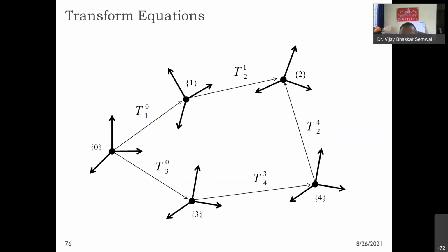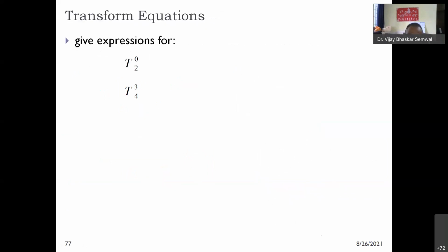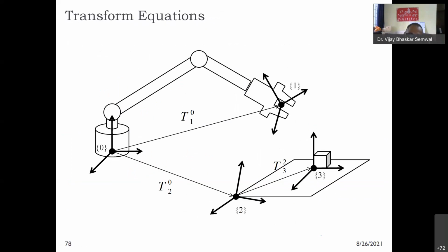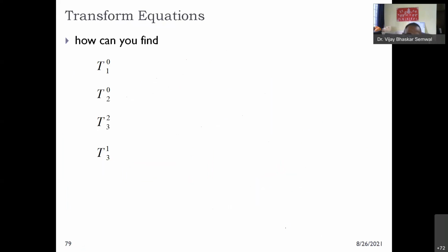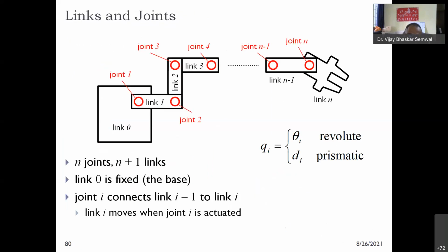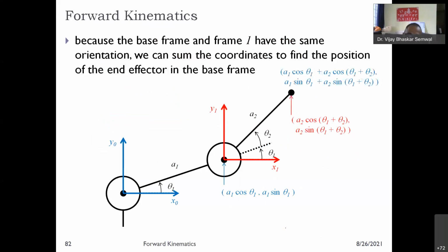matrix equation. So in forward kinematics, we are moving like frame 1 position with respect to 0, frame 2 with respect to 1, and this way I'm going. Finally, this way I'm calculating forward kinematics. So like this object, you have to pick. This is the model with respect to frame 0. So what is the position of frame 3 with respect to 0? First we have to check the joint 1 position, joint 2 position, and where the end effector hand is, where the object is, and the camera position is required. This you can do through link and joint. This is forward kinematics.